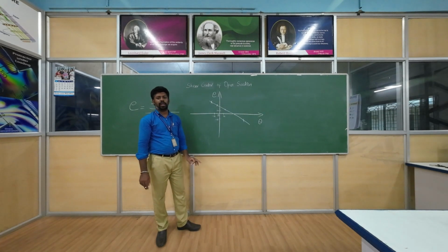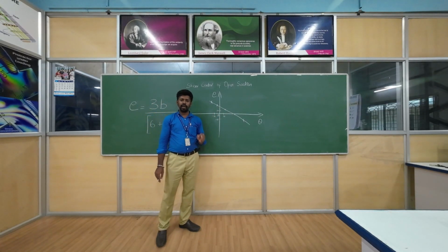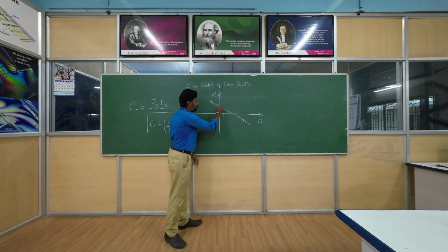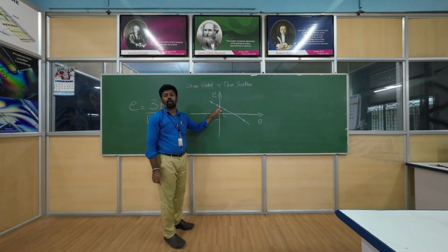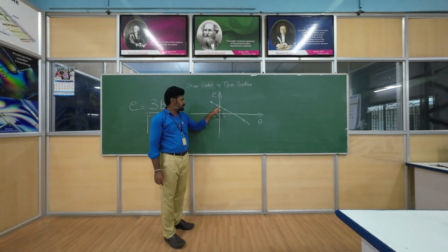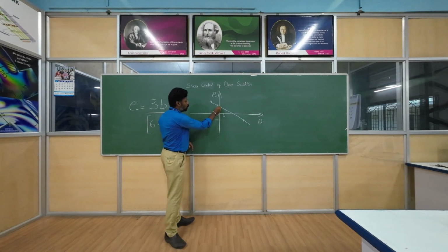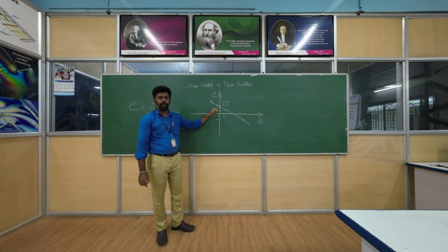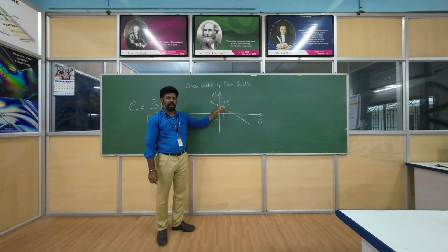So now we need to identify the location of the shear center of the given channel section. So we all know that in the beginning I have mentioned that shear center is a point where I have bending without twisting. That means there is zero rotation. So now you can observe closely the graph. So this is the point where I have zero rotation, that is theta is 0. So this point is called the shear center of the channel section. So from here it is around roughly 20 mm. So if you plot the graph, you will get this value.